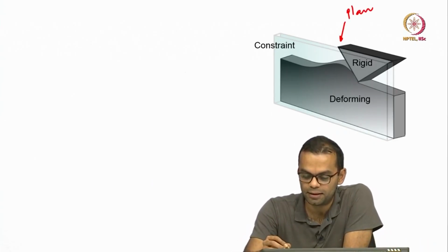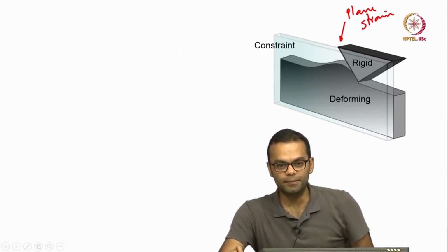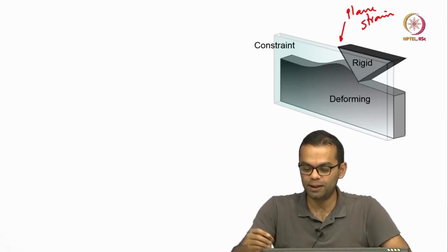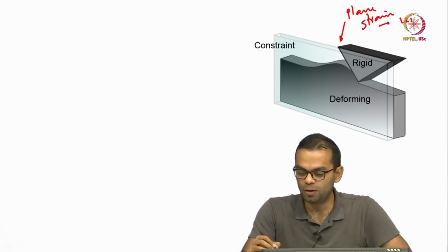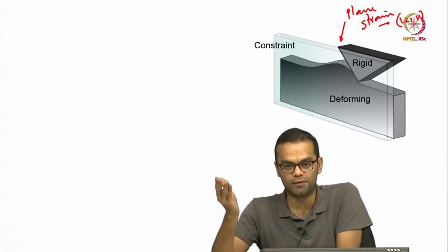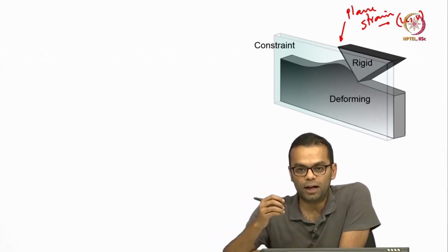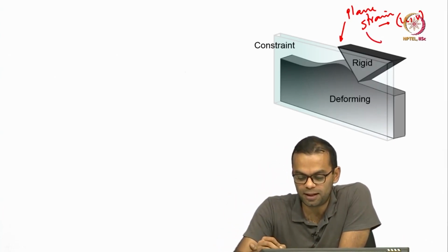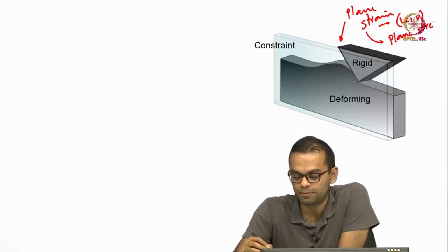I think I mentioned this in the introduction. This means that you only have components u and v, you do not have a w, or an out of plane displacement component. So, you do not have gradients out of plane either, and you must contrast this with a plane stress problem, right. In solid mechanics you have to make a distinction between these two.